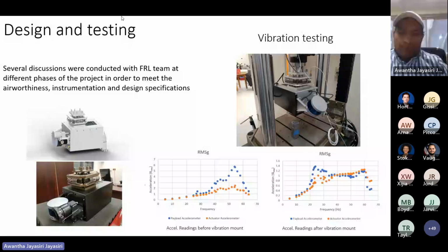Let's have a look at the perception solution, for example. It has three main subsystems: the VLOM subsystem, the place recognition subsystem, and the labeling subsystem. It represents an improved simultaneous localization and mapping solution. It's a SLAM solution, so it fuses sensor information at different rates and fuses GPS data while it's available.